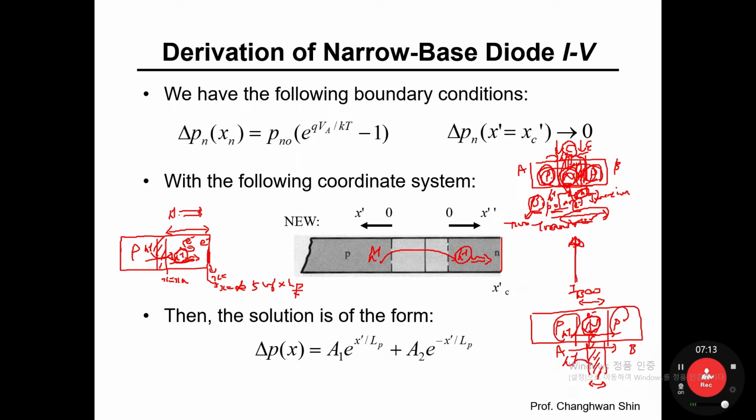The holes are injected into the n side, and all the injected holes should be fully recombined with electrons there. However, because the physical length of the n side in the middle is not long enough, part of the holes would still be alive and get to the second p side here. So what if all the injected holes are recombined with electrons and nothing can be delivered to the second p side? Then we may not form the current flow from p to p, which means that no current is flowing.